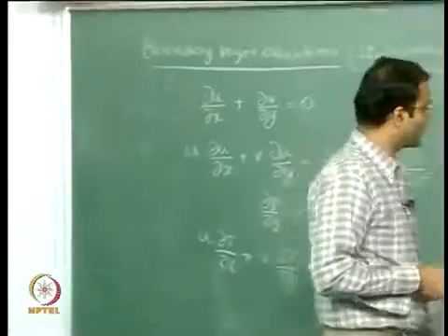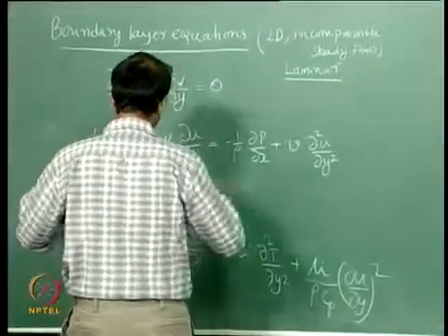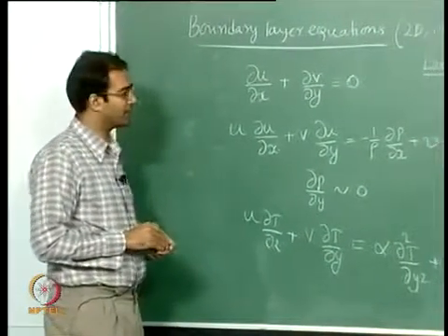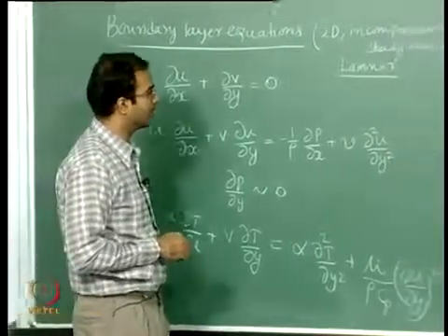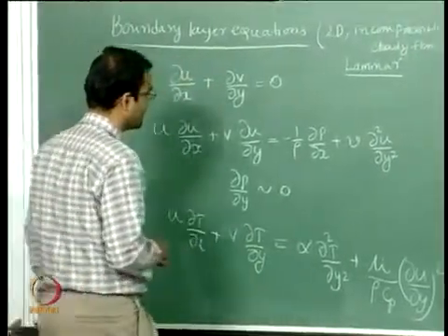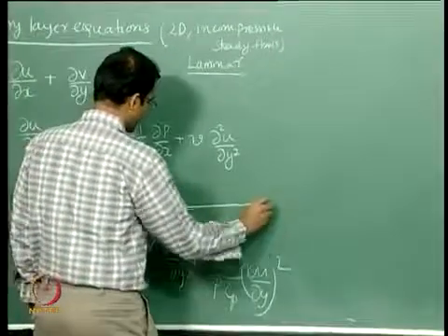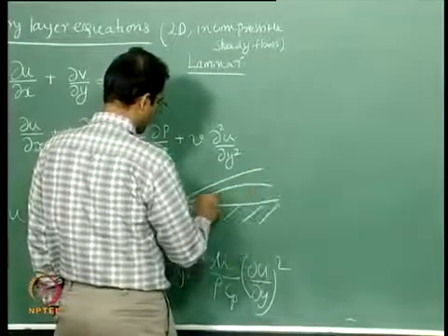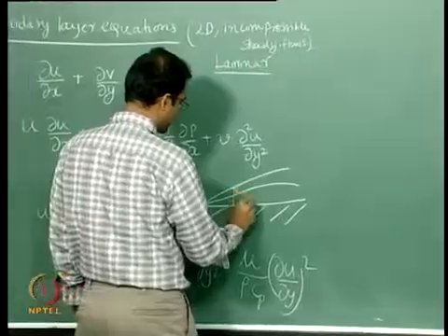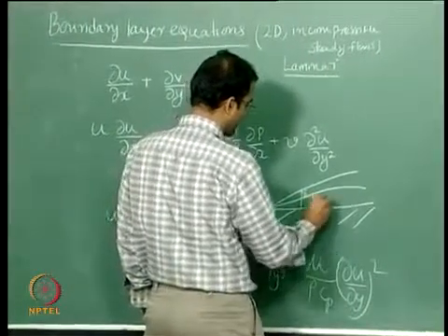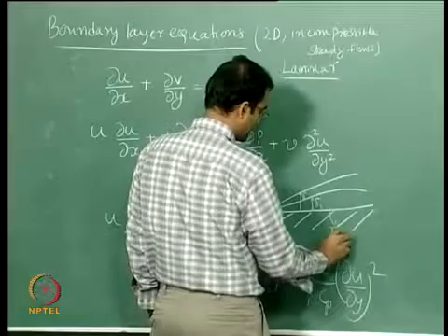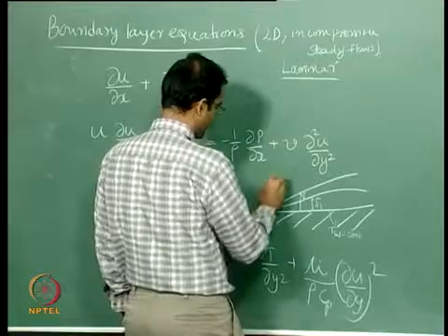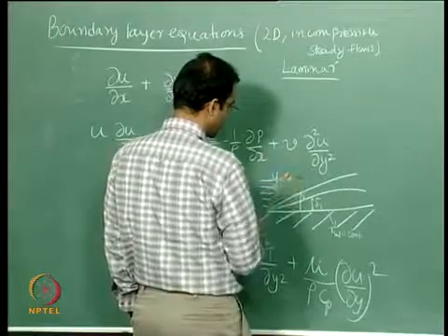Now in order to solve these equations, we need definitely some boundary conditions. These are partial differential equations. So can you tell me what are the boundary conditions that we can apply? Say we take the case of our flat plate, the same as yesterday, we have a momentum boundary layer of thickness delta, a thermal boundary layer of thickness delta T, and the wall is maintained at a constant temperature, and you have a flow with u infinity, T infinity.